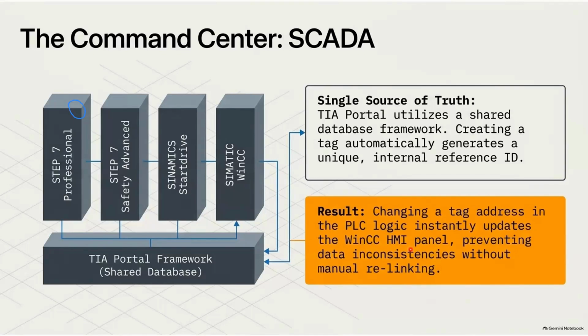And the software, whatever they provide, is with respect to tags. Tags in the sense, just now I said, assume this is our SCADA, and here you have one tank, and four tanks are there, and this is the motor. For this tank, we need to know the tank level, and we have to provide one tank name and a few other sensors. Assume there are a total of 5 sensors for this one, and 5 here, and for this motor another 2 sensors are required maybe. So total 22 IOs are there.